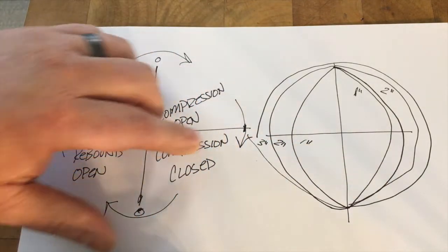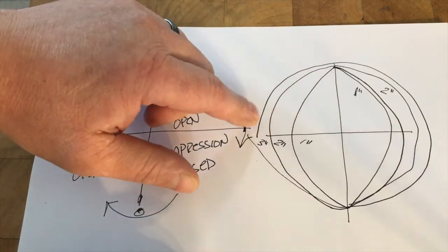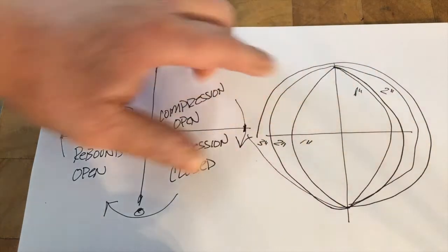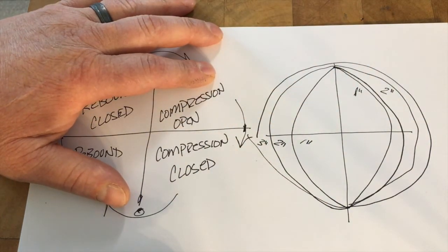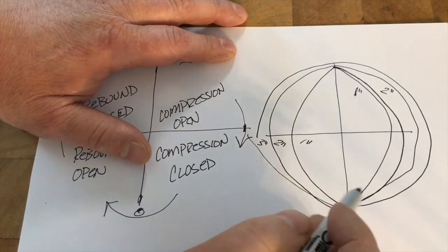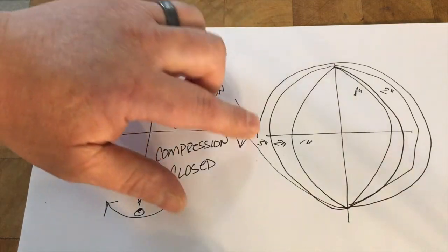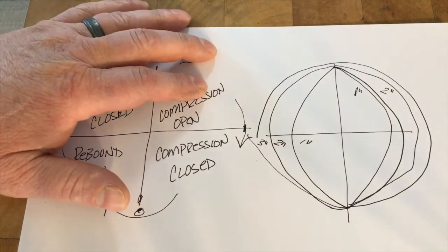Like I said, a linear shock, a pure linear shock, I should say. All these lines will be the same. I haven't seen in a very, very long time a purely linear shock. There's always a little variation. Whether it's going to be bleed or something else, there'll always be a little variation in the separation between the segments.